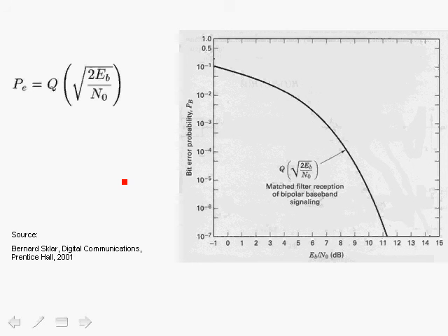So to summarize, we've been able to design a baseband binary digital communication link, and we have derived the probability of error versus Eb over N0, the energy per bit divided by the one-sided power spectral density. That is, we're also relating it to the signal-to-noise ratio. So this is a major accomplishment in terms of understanding a baseband digital communication link with additive white Gaussian noise.